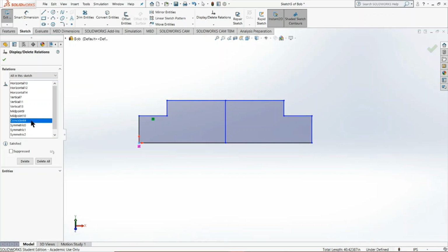So say we have this coincident relation here. This is just between two different lines. This is sort of implying that these two lines cannot ever be apart from one another. So they always have to be touching. They always have to be intersecting. And to get rid of this relation, you can delete it. Pretty much what that'll allow you to do is, rather than having these two joined together, you can move both of these lines quite freely. So that's something to play around with.